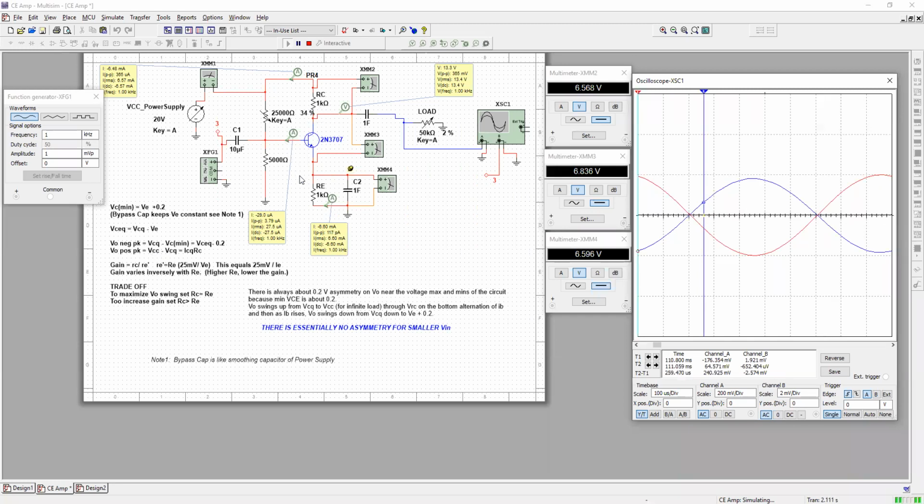So the base current is so low that it chokes all the current in the transistor. There's no current flowing here. And you're going to see that all of the voltage will be at the transistor, the collector and emitter voltage. So remember that VE is staying constant because this capacitor is providing the current when there is no more current coming from the transistor. So the voltage that the transistor increases by is the voltage at the collector.